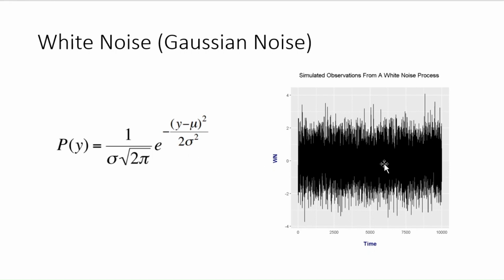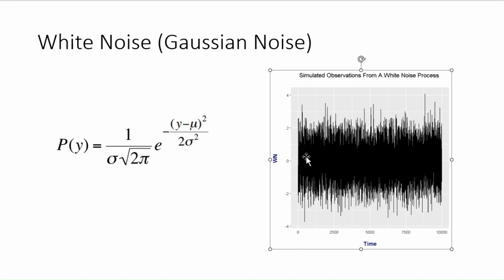In time series, it looks something like this. If we say mu is 0, that means the noise is going to be centered around the 0 axis. And this sigma decides the fluctuation of this noise around the mean, that is, these amplitudes. If sigma is a low value, these amplitudes will fluctuate in a very narrow band. Otherwise, if sigma is a large number, then this signal will have very wild amplitude fluctuations. And that's how white noise gets generated. So let's switch over to Python and try to generate this noise.